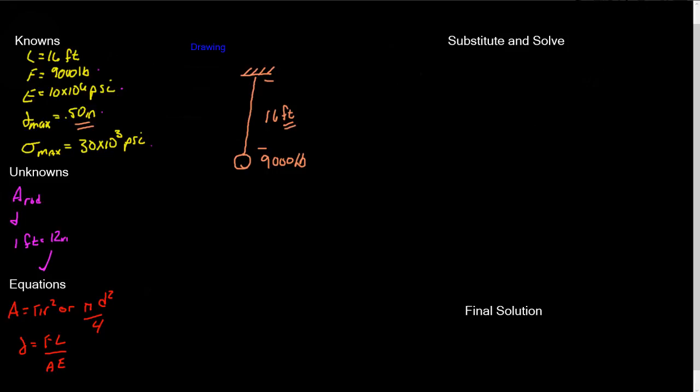So the last equation here is really a rearranged equation that relates our stretch of the rod to the force in the rod, the original length, divided by the area and Young's modulus. And you go, well, how the heck did he get that? So let's take a quick look and step back and pull that stress-strain relationship up.